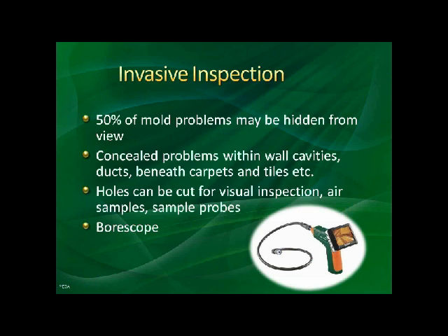There are invasive inspection techniques. You could use a borescope and look through a receptacle cover behind the wall. In certain areas, you may lift a ceiling tile and use that. The new types of borescopes have come a long way, and they have video and picture capabilities. As you see, this is actually a BR200. You can take that screen off, set it aside while you're using the scope, and video your inspection.